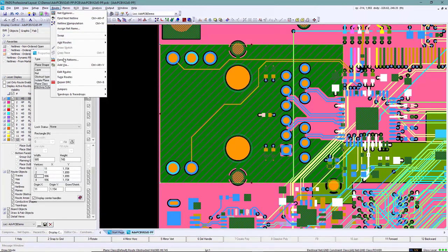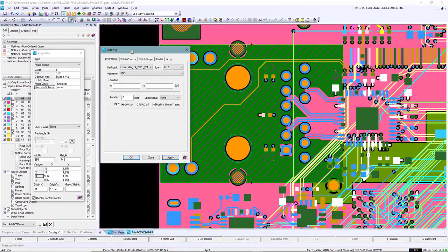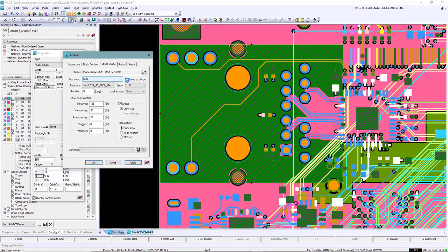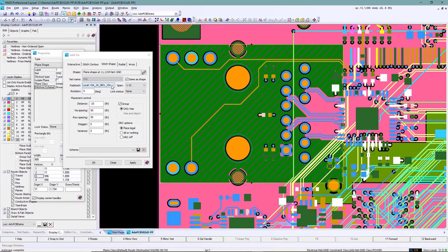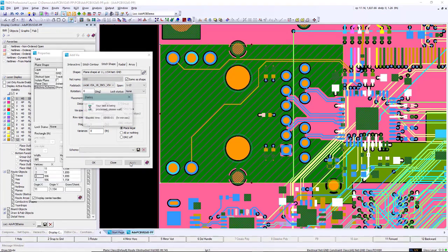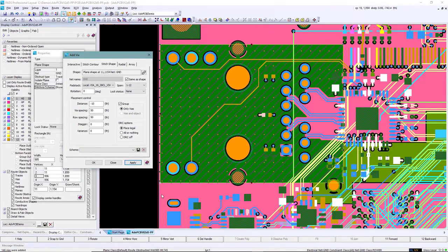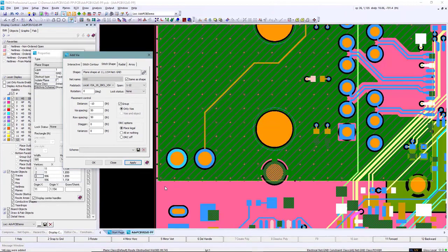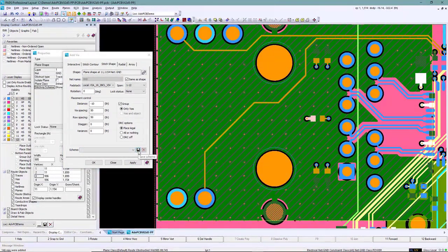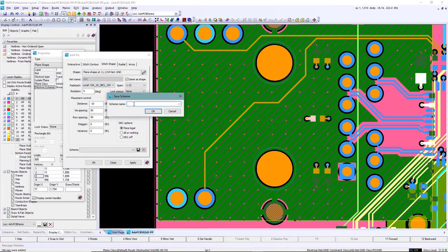If you've been designing PCBs for some time, at some point you've had to fill a plane area with vias or place guard vias around a trace. When placing one by one, this takes forever. We have a requirement with our design to create a ground plane directly under our RJ45 connector and fill with vias. Using stitch shape, we can play with several scenarios and choose the most appropriate, as it only takes a few seconds to process. In case we create more plane areas requiring via fill, we'll save this configuration.